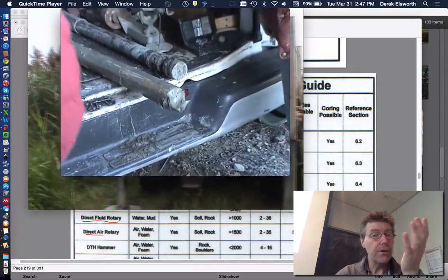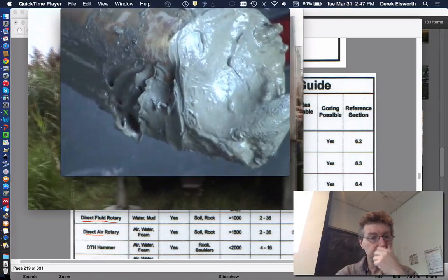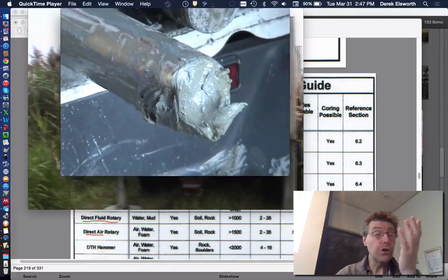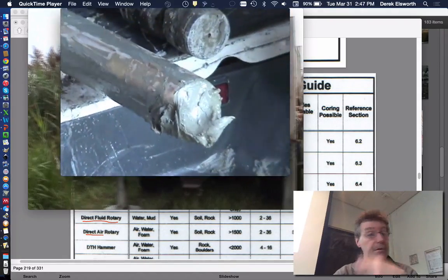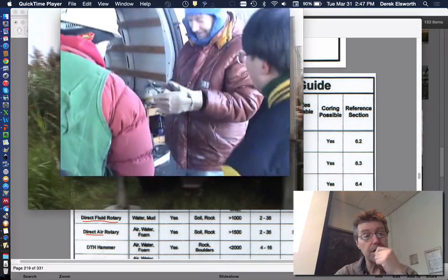You'd seal it by pouring molten paraffin wax on it to seal the moisture in, and then you'd pack it off back to the labs to extrude the core, to maybe do some permeability measurements on it if that was important for the project, or air entry or liquid entry pressures.